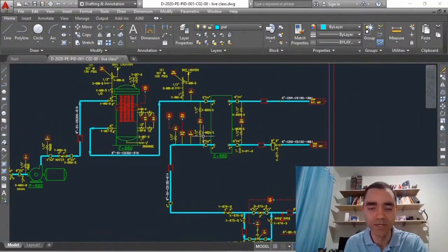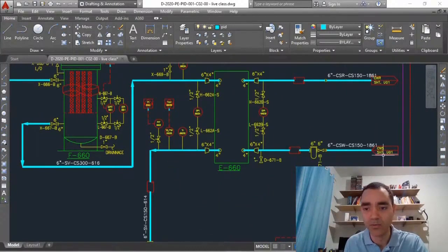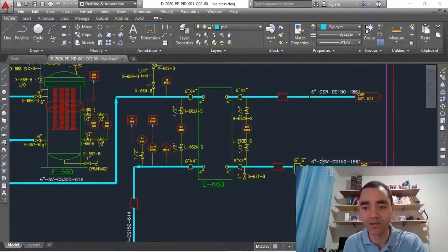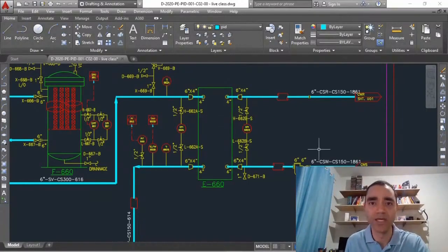And to guarantee the heat exchange, we have a cooling water supply and a cooling water return. So we can imagine here, based on the fluids that we have, that this is a process of cooling down the fluid and not of heating up, because if we have cooling water supply, it means that its service is for cooling, not for heating. On the other hand, if we had hot water supply, it would be for heating up, not for cooling.